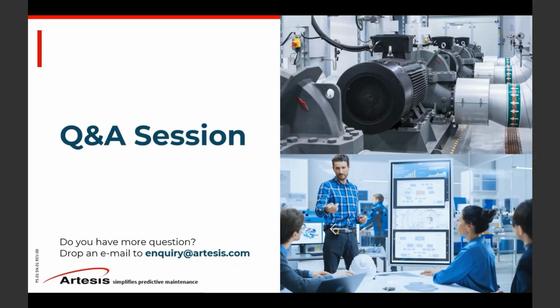So how accurate is this AI compared to the previous version? The AI is currently, I would say, around 80-85% accurate. It's comparable to an experienced diagnostic engineer with 3-4 years of experience. It can detect easy problems really easily, and the accuracy there is 100%. If you have simple misalignment, bearings, fan issues, or gearbox issues, it's pretty much spot on. But when you get into more complex assets, of course, the analysis is not as accurate.